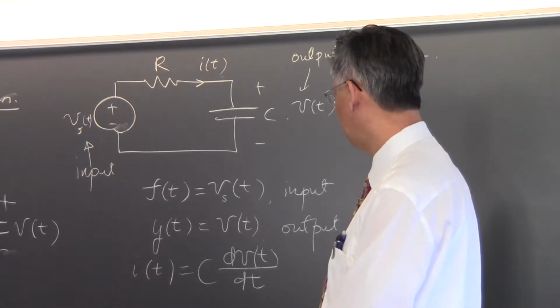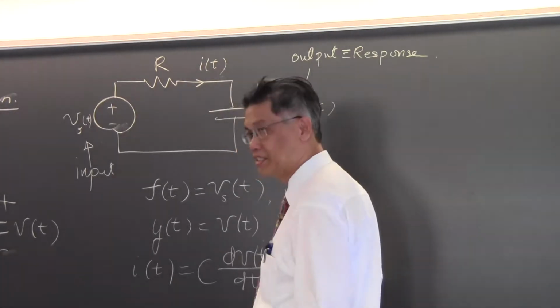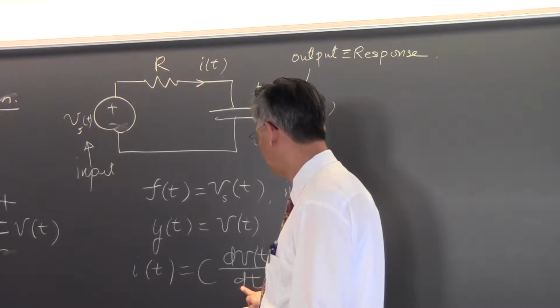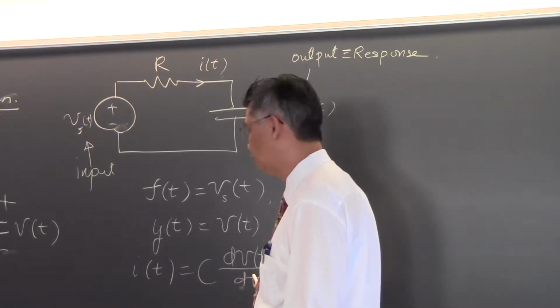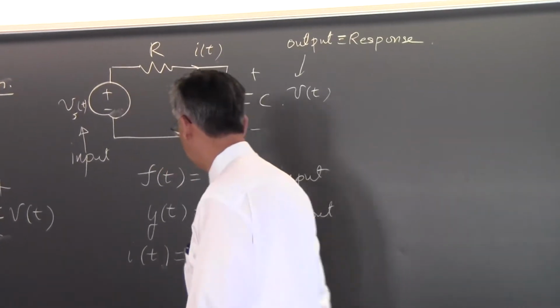One thing to remember is that in a capacitor, the voltage cannot jump. Okay, the voltage cannot jump. If it does jump, the derivative of it will give rise to infinity, then that cannot be true, because that will give rise to infinite current.